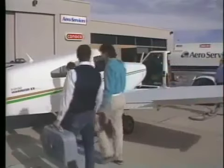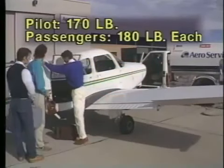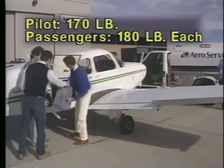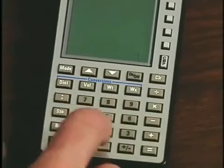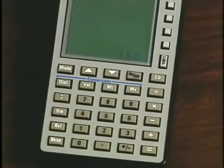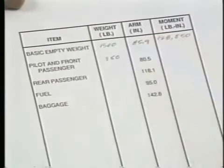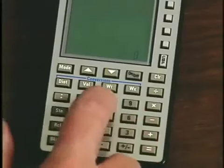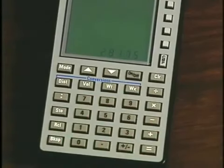As a sample problem, assume you weigh 170 pounds and you're going to be carrying 2 passengers who each weigh 180 pounds. Since one of the passengers will be sitting in the co-pilot seat, you need to add your weight to that of the passenger. The result is 350 pounds. Since the arm for the pilot and front seat passenger is 80.5 inches aft of datum, the moment is 28,175 pound-inches.